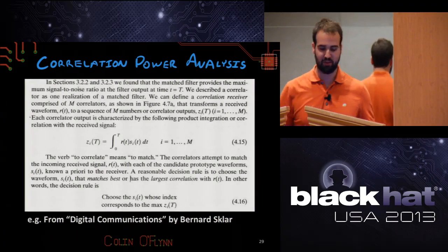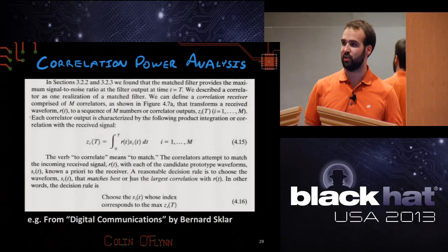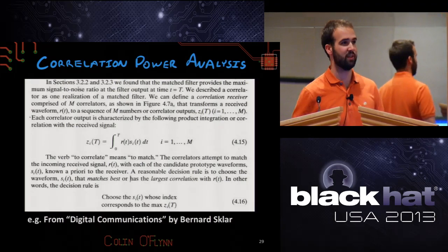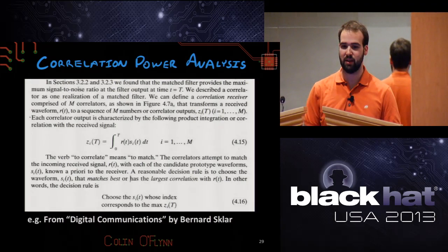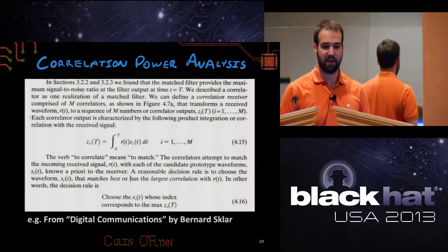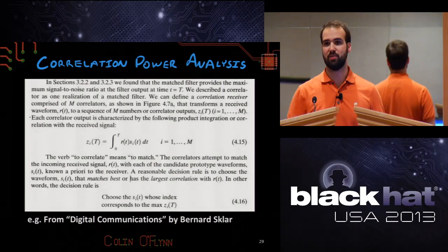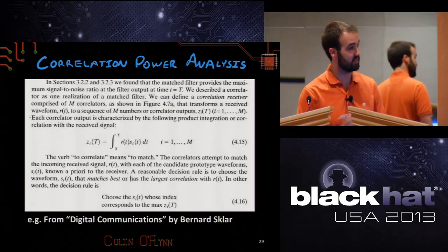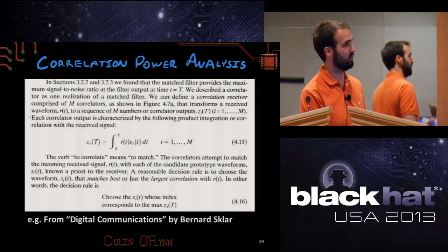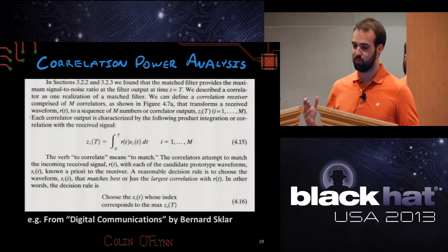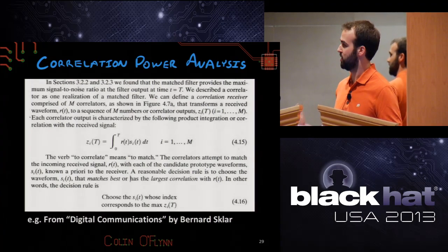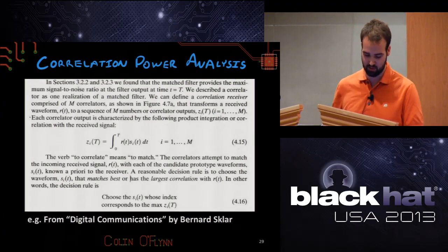You might notice this sounds familiar if you're an engineer type. This is actually what's known as matched filtering. It was effectively rediscovered in the field of side channel attacks. Matched filtering is exactly this, and it's used in radio receivers to decode what signal was received. And this has been known for many years, 20, 30 years, I think. So the point I'm trying to make is a lot of this isn't really advanced. The actual theory behind it is quite simple and quite straightforward.